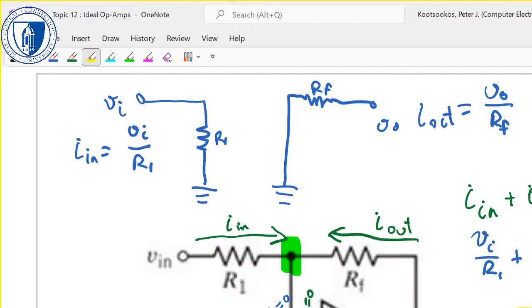Now the sorts of places you use these in real life are if you've got a strain gauge, and strain gauges give you a bit of voltage but not much, and you want to amplify it. 741s themselves aren't great for audio. You can use them for audio to make pick up from a microphone louder, but they're not great.